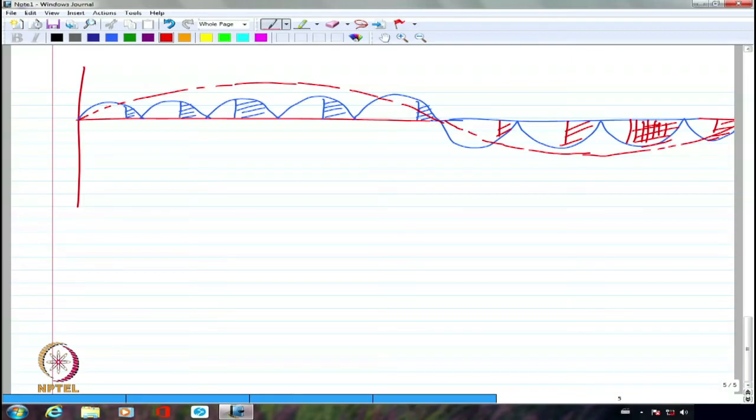That will make sure that what I apply as the voltage is somewhat sinusoidal. And the same thing has to be replicated for B phase, shifted by 120 degrees, and again duplicated for C phase, shifted another 120 degrees.